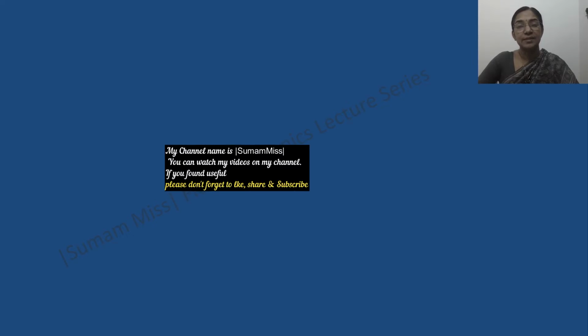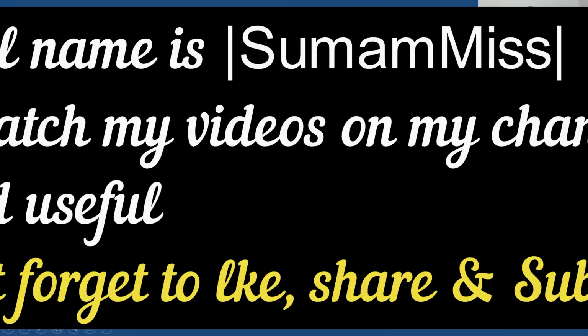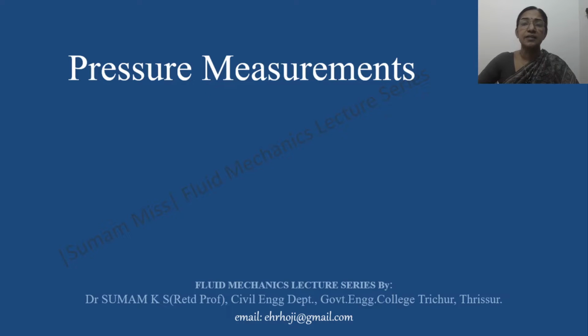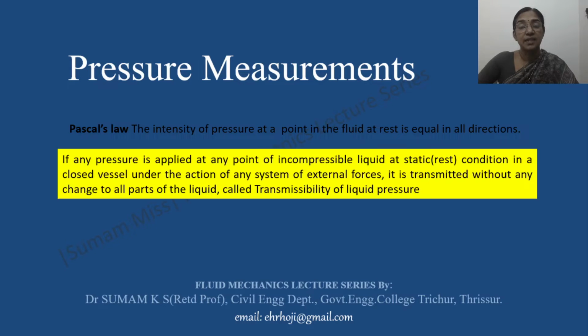Today we are going to discuss the measurement of pressure. Before going to the discussion on the measurement of pressure, let us start with the pressure variation in a static mass of fluid. Pascal's law states that the intensity of the pressure at any point in a static mass of fluid is equal in all directions. Similarly, transmissibility of pressure states that if certain pressure is applied to an incompressible liquid enclosed in a container